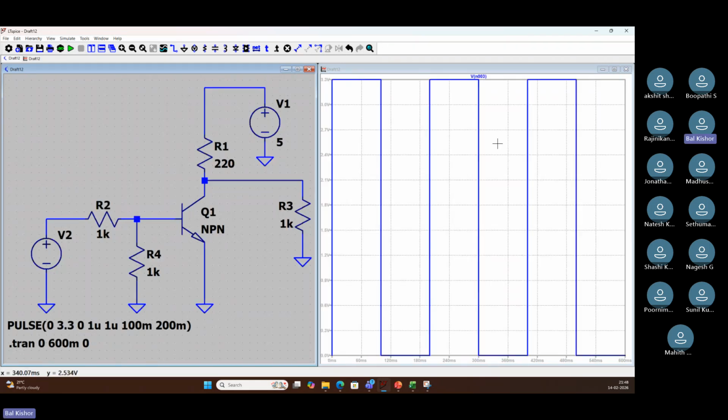So if you see, this is my input voltage, which is a 0 to 3.3 square wave, right? And then we have the VBE, how much is it going to be? It is coming from V to BE. So it will be 0.7, right? So it is coming 0.7. Okay, 0.7 or 0.8 will be there. And then you see the output. So output, what will happen?